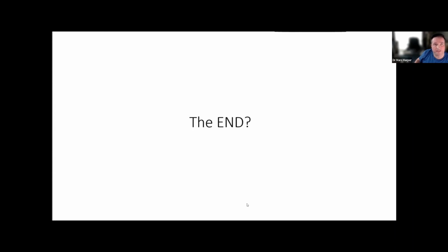For Wi-Fi, because you're in a building, with all the reflections, if you have a very high gain Wi-Fi antenna, it gets averaged out because of the internal reflections inside the building. So it's not as important to have an omnidirectional Wi-Fi antenna as it is for cellular, because cellular is generally outside, or you just don't know where the cell tower is. But in Wi-Fi, you can get away with higher peak gain antennas, because the building and the reflections from whatever room you're in average that peak gain out for you in terms of what happens to the signal.